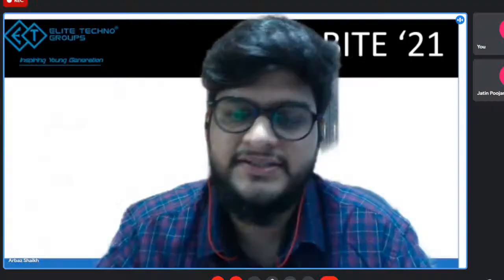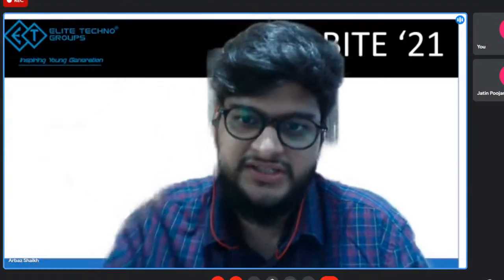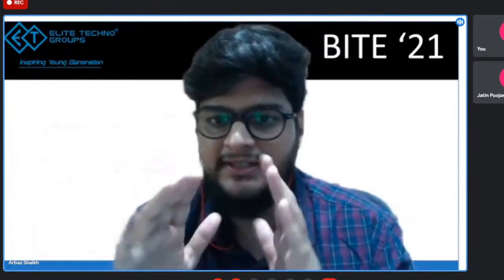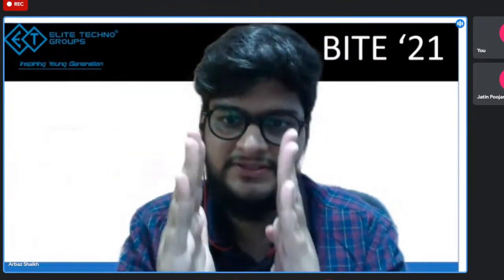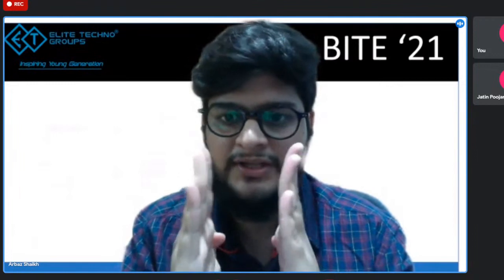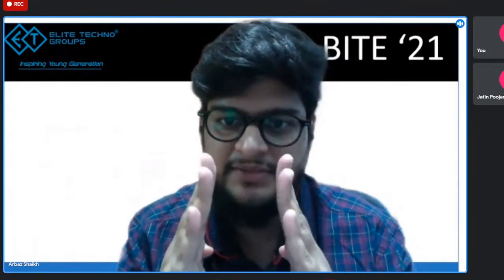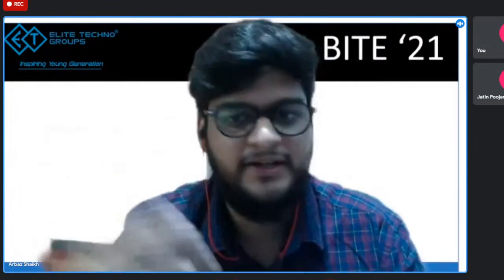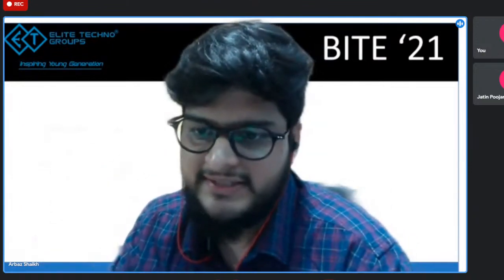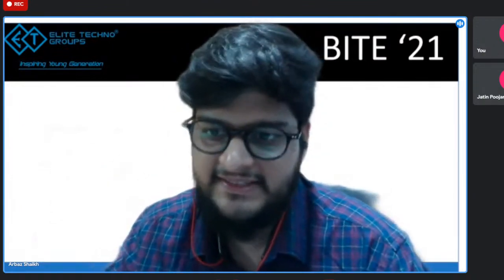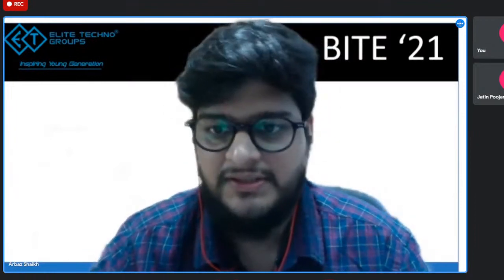And one more thing, I guess you forgot to mention, was toe. When you see the vehicle from the top view, if these two are the wheels, they will never point straight in the direction of motion. They will either be slightly inwards or slightly outwards depending on the application. So these are the three conditions that are used in suspension.